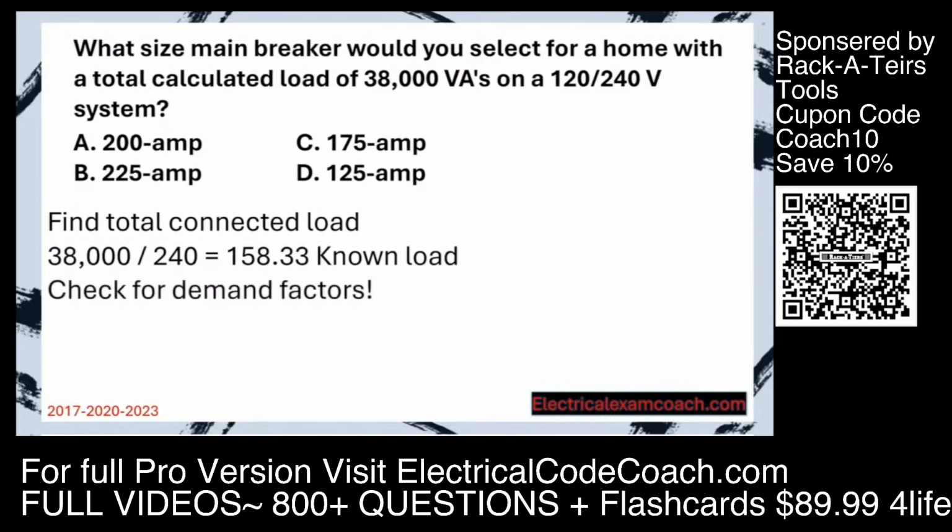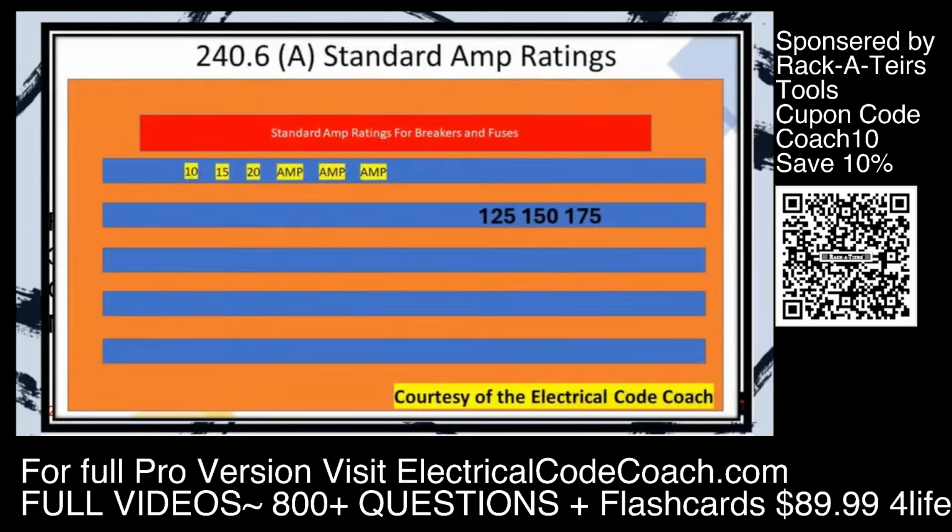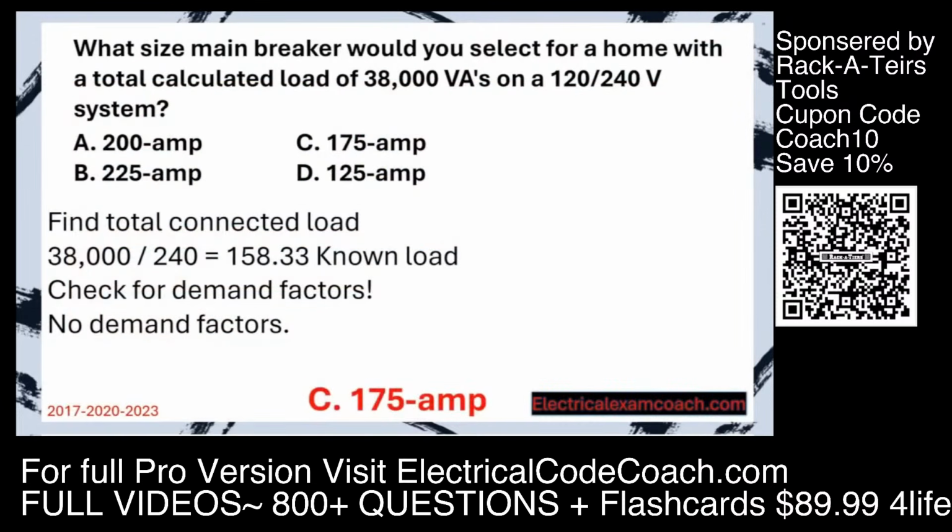Now we check for demand factors. And like we said before, there are no more demand factors on this calculation. We head over to table 240.6(A) and we choose the next standard size breaker. And in this case, it's 175 amps.